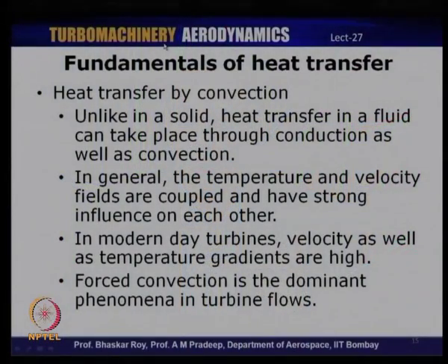Now, in the modern day turbine scenario, the coupling is even more significant because velocity as well as temperature gradients are very high. And in that scenario, the temperature and velocity fields will have a very strong influence on each other. A turbine blade which has been designed for cooling methods will involve forced convection, and that is the dominant phenomenon of heat transfer in turbine flows.